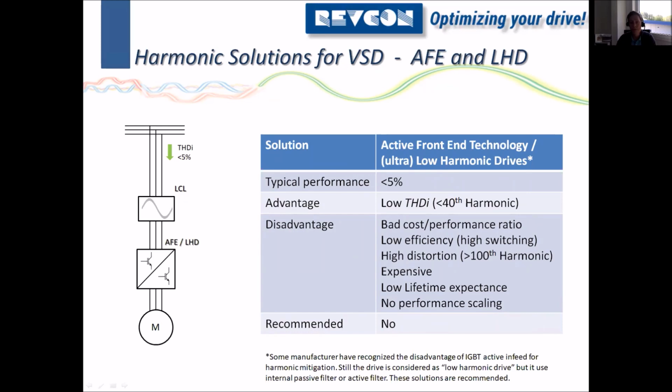The next one is the active front end LCL, a combination of active input and LCL. The performance will definitely be below 5%. They are quite clean in the complete spectrum. They are quite clean in the lower power area, so up to 20%, you would typically see a quite good THDI.